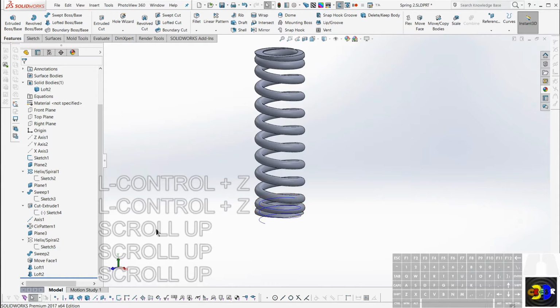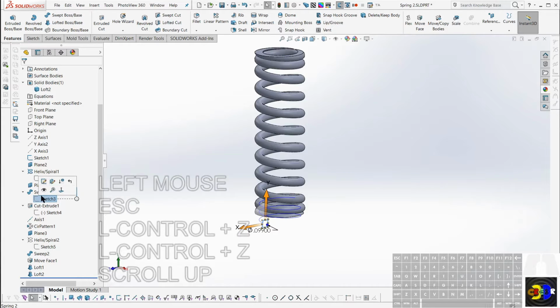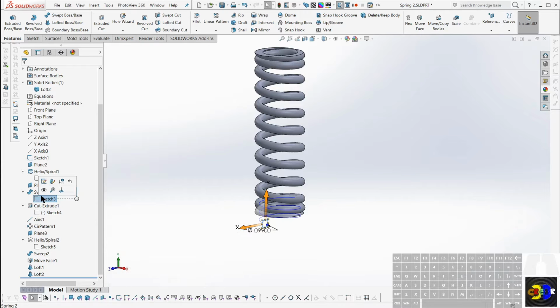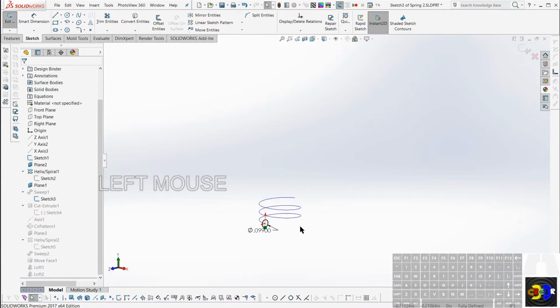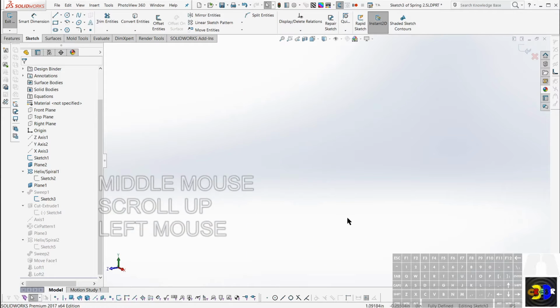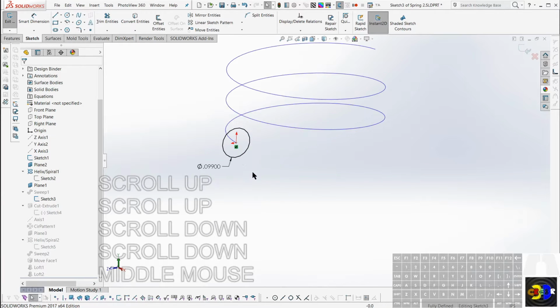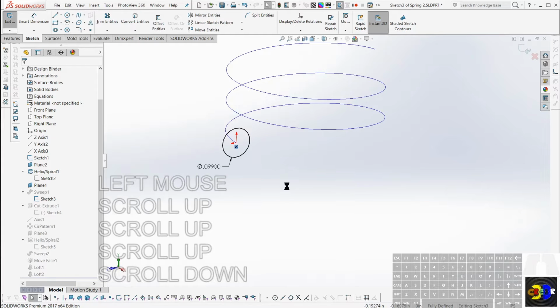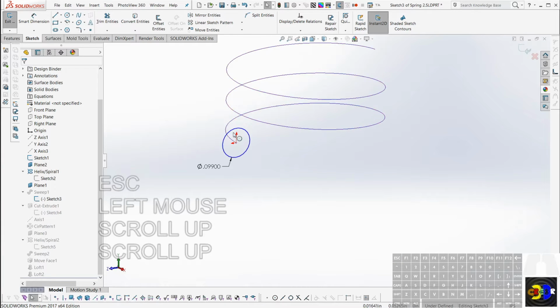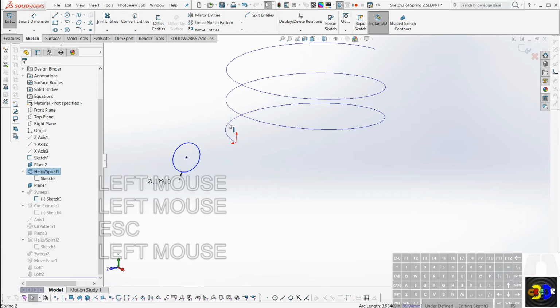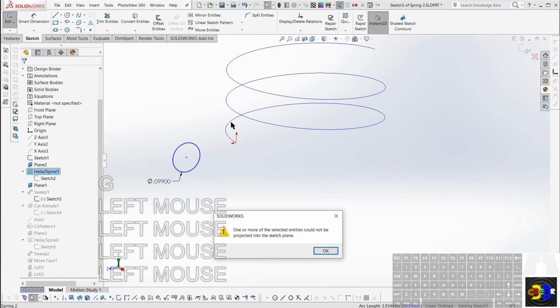There's almost not a good reason to not just do it that way, but let's do it properly so it's easier to control and it'll be a simpler model. So I basically need to undo that, get rid of that constraint, allow that to move off, and I do want to again project this geometry with the G key.